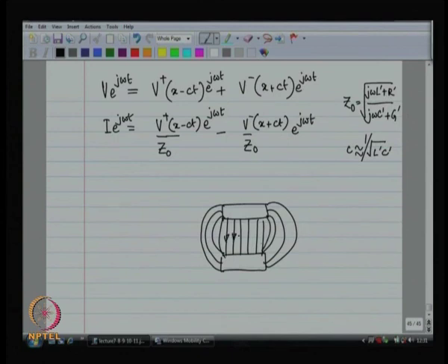So, thicker the plates, more fringing. Fringing is going to happen along the perimeter. So, as a result, if I want to just look at the fringe capacitance, then the fringe capacitance is proportional to the perimeter, and it is also proportional to the thickness of the plates. Then we talked about different ways to make capacitors.